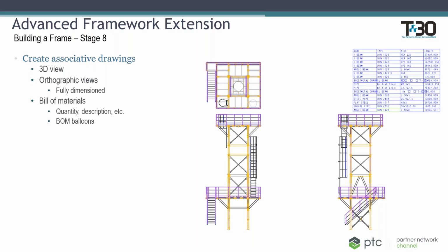So AFX includes a drawing function where it creates it based on an assembly, top-level assembly, or a part in particular. So this will capture all the different hardware used, different sizes, profile standards, and all to give you a comprehensive BOM in the end. So again, the intent here is to optimize your framework design and to make it a lot more efficient to work with these large assemblies.